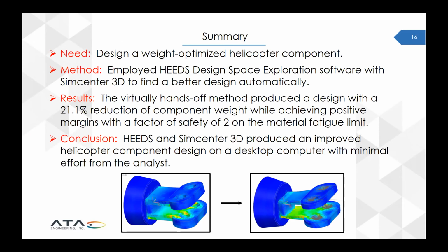Yeah, and I think I have two thoughts to add on there. My first is that it would be common for us to say, well, we don't want to look at results and elements that are attached to RBE2s because those introduce artificial stiffness. You can get some unrealistic stresses there. So maybe you select the elements, like in this case, around those bolt holes. And if you lock that mesh, then that mesh wouldn't update whenever it would remesh based on geometry changes. So I think you could specify those element IDs as elements to ignore in the optimizer, and I think those would stay consistent.